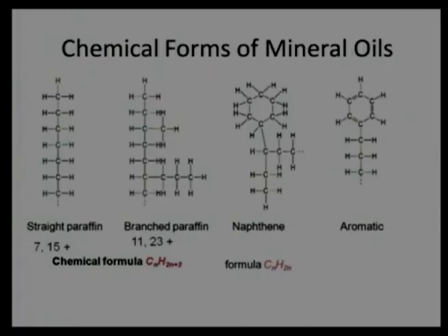I am just reversing. They have a low solidification temperature. They will solidify at a lesser temperature compared to the paraffinic oil. So, for low temperature application, naphthenes are good, but they will not have that structural or thermal capability to sustain high temperature as a paraffinic oil. So, both have merits and demerits.